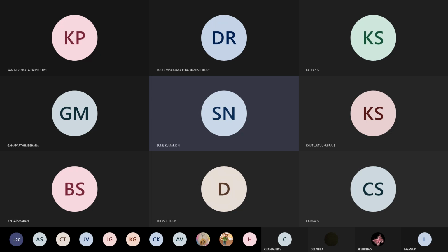So we need to say that these two components are there: half Kn into VGS squared. We know that already. We are going to take the gate to source voltage as a small gate to source voltage. Whenever it is the square of the small signal voltage, the resulting term will have a very small value. So we can say that this is going to be very small compared to this value, Kn into (VGS minus VT) into vgs.